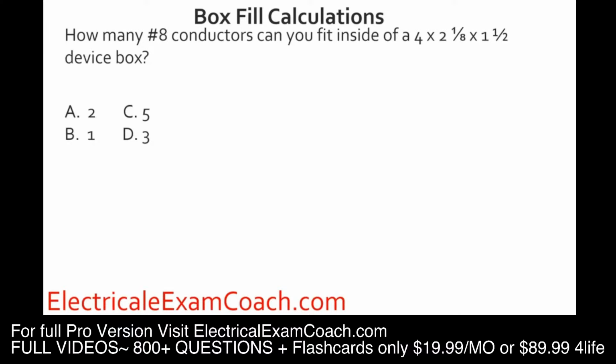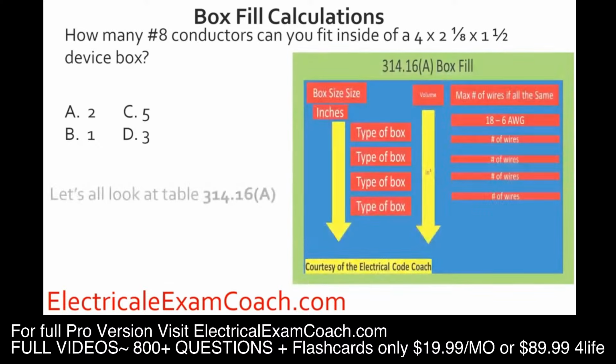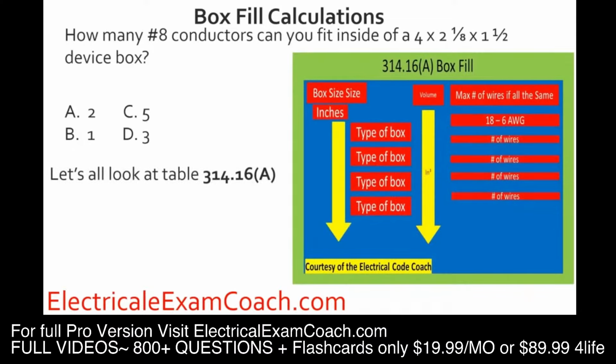How many number 8 conductors can you fit inside of a 4 by 2 1/8 by 1.5 inch device box? We head to 314.16(A). We're going to find our gauge wire, then come over and find our type of box and size. Make sure we do everything correctly, and we're going to find that it holds 3.